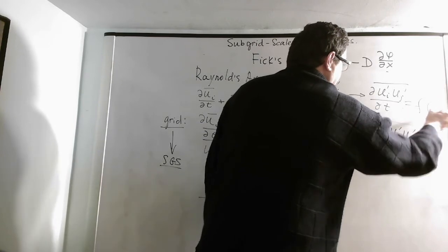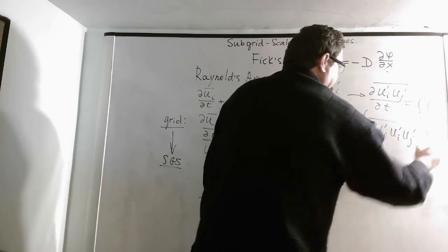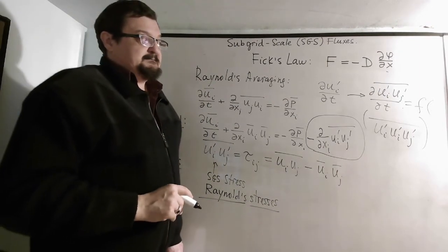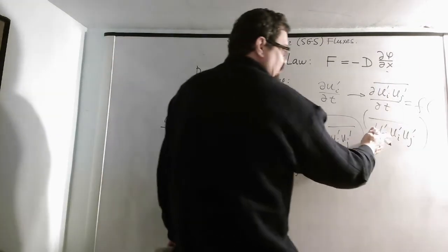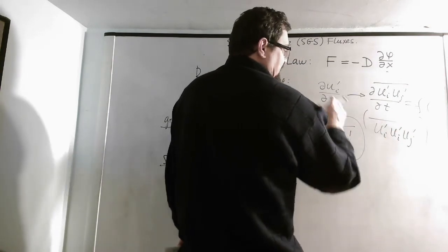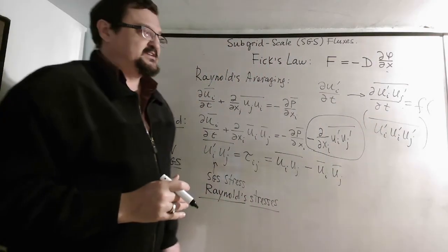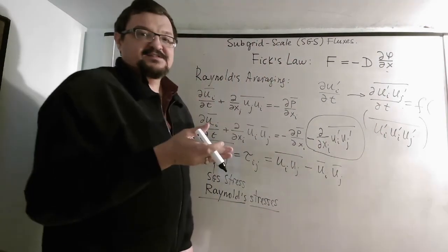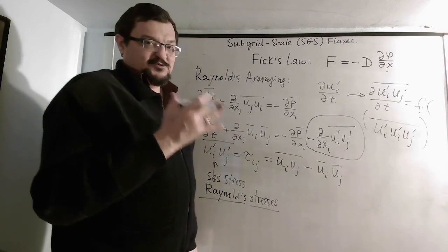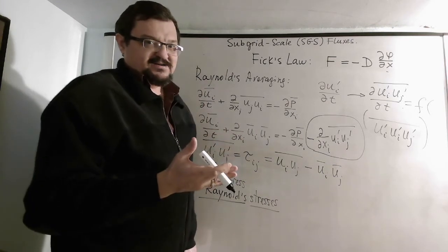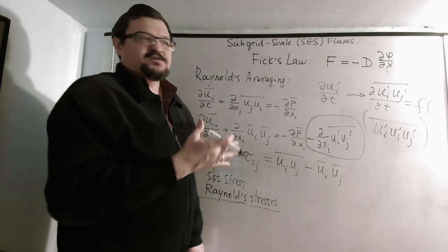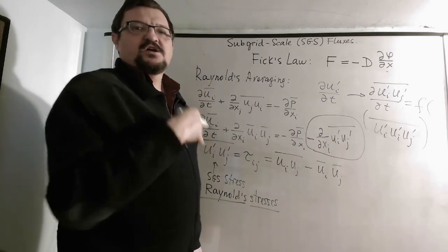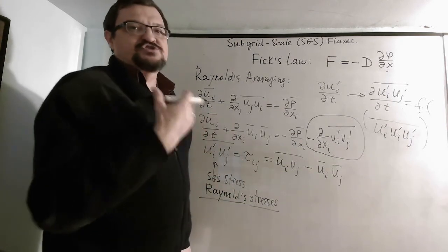This is a function of this. And if we were to write equations for this triple moment, or third moment of velocity, on the right hand side there are going to be, as you guessed, fourth order moments, and so on. So the process is basically infinite. You cannot close the system. So that's basically the closure problem.